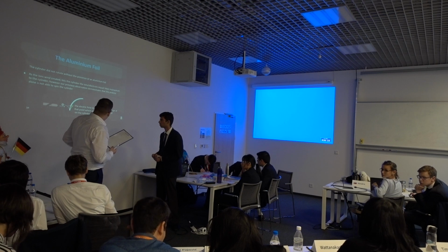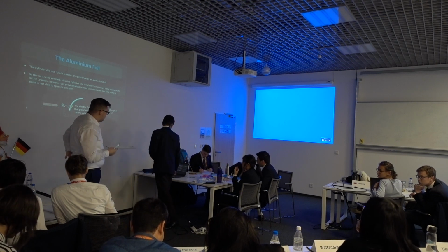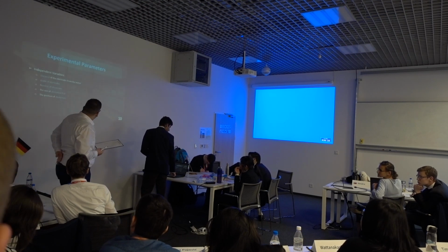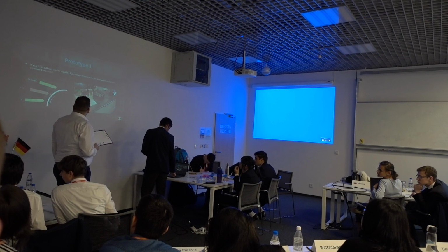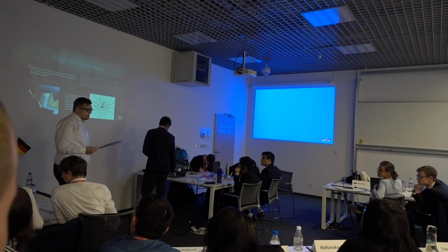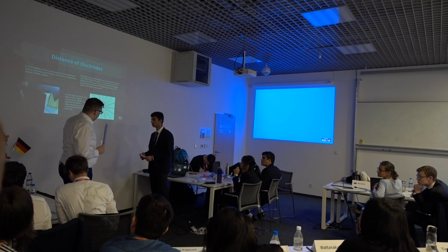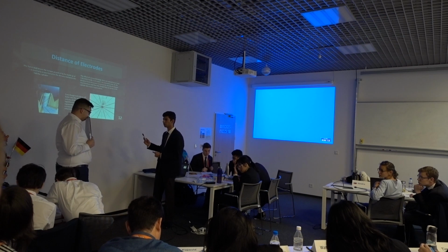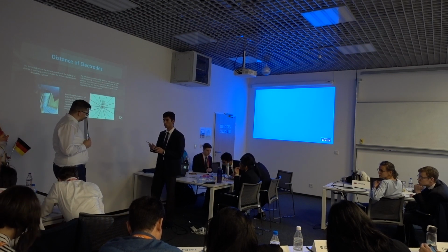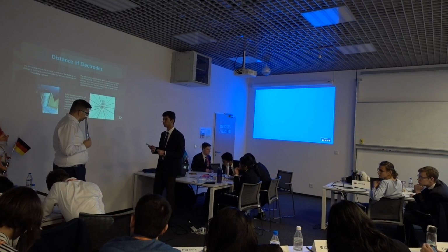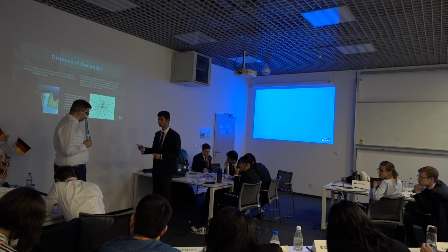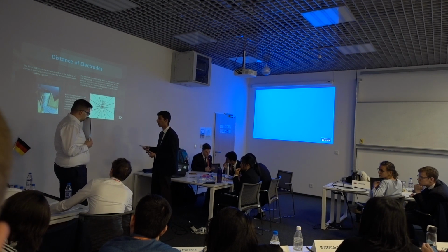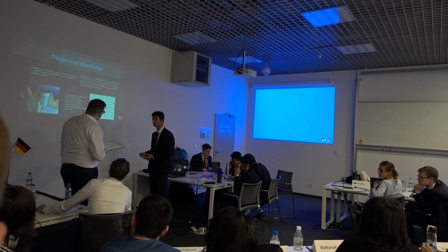So we can look at the distance between electrodes, between electrode and the rotor. You stated that the decay shall be exponential. What is your reasoning behind this? It is simply due to the avalanche effect that I previously mentioned. The free electrons that are accelerated by the electric field have a chance to be imparted enough kinetic energy to hit a nearby atom and ionize it.